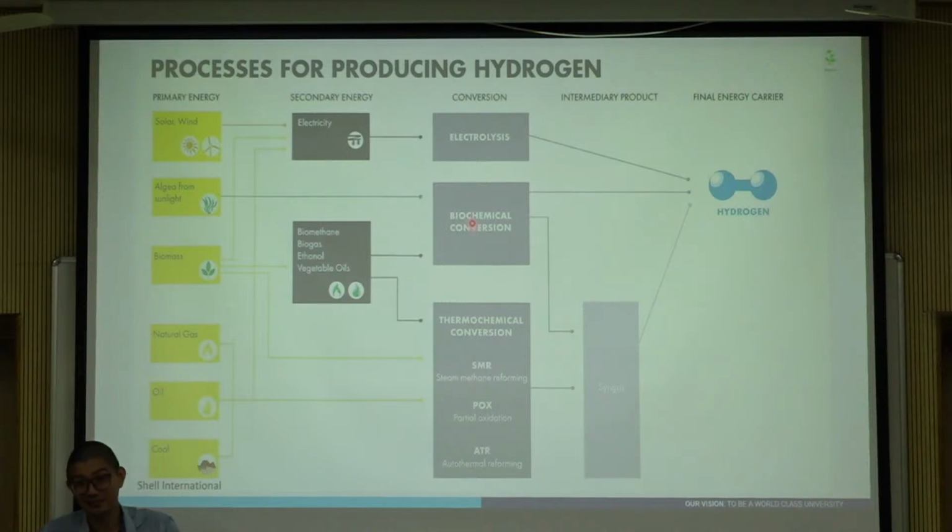This is another challenge. That's why people prefer to use natural gas, not any other type of biogas or CO or whatever, because it's very pure hydrogen from the methane. Natural gas is particularly methane. So if we go through biomass, a lot of the other gases that we produce make it very hard to separate. This is another problem facing the biomass gasification process.